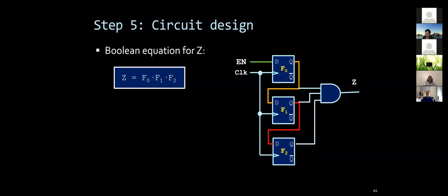Okay, sorry. So how does one flip-flop store 2 states if one state consists of 3 bits like 1, 1, 1? So one flip-flop stores 0 and 1, right? So it stores 1 bit. It doesn't store 2 different states. It stores a bit of a state. And the state is built out of multiple of those bits. So 3 flip-flops, right? It can essentially store 2 to the power 3 different binary values that represent 8 states. So Z, did I answer your question?